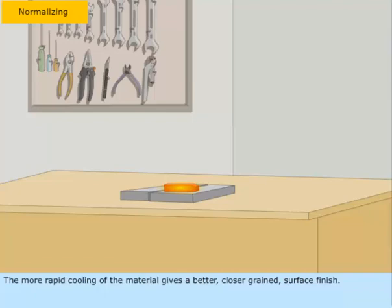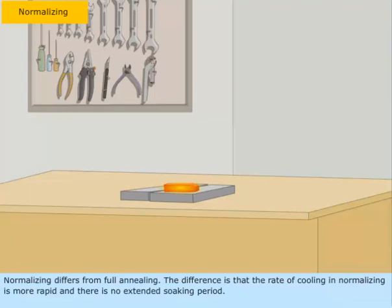Normalizing differs from full annealing. The difference is that the rate of cooling in normalizing is more rapid, and there is no extended soaking period.